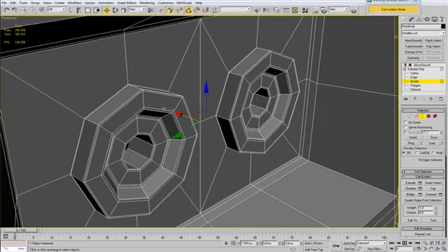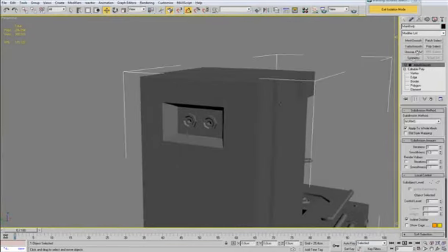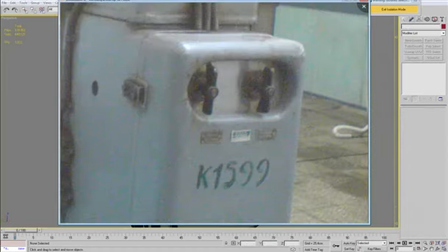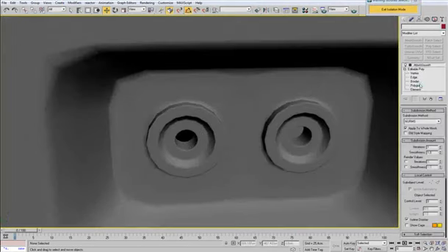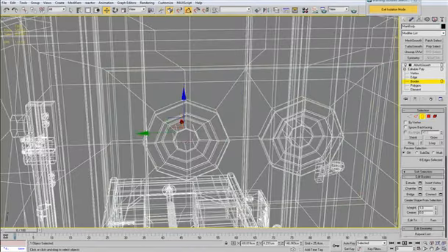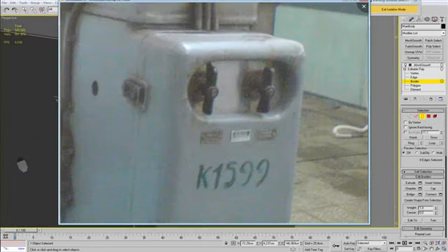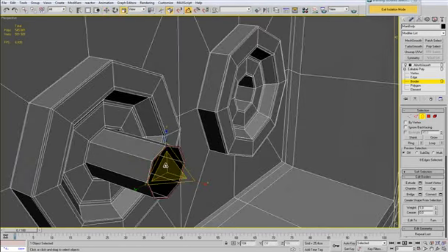And also you'll see that I don't only do the overall shape, I also try to create the edge loops that I need for hardening the sides, because if I do them now while I'm creating the shape, it's actually easier than to go ahead and get inside the shape after it's done and try to select all of the rings or the loops there and try to create all the edges that I need to harden the sides.